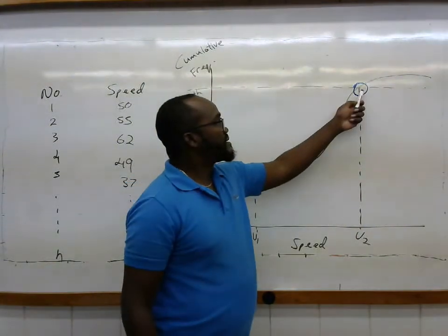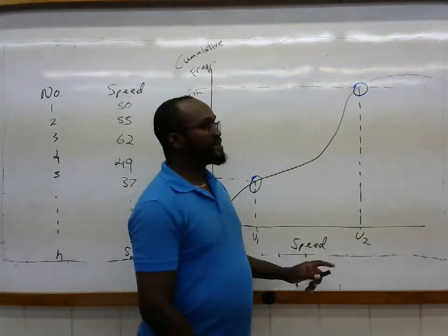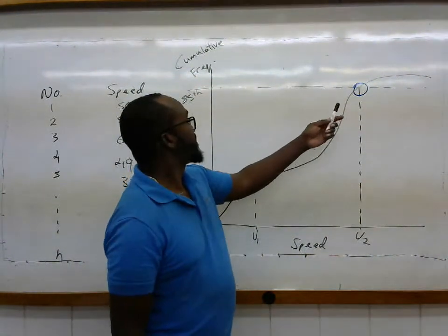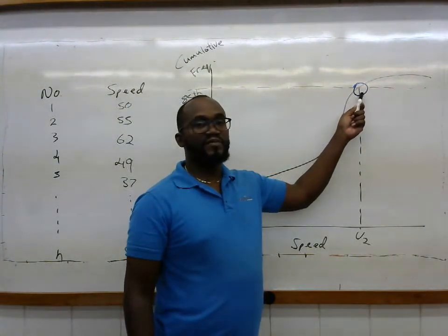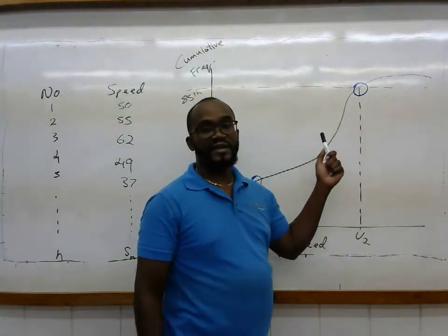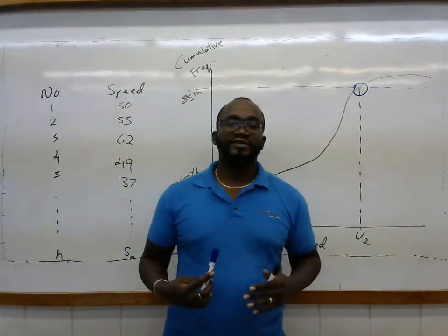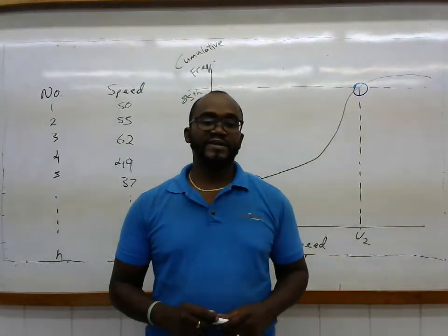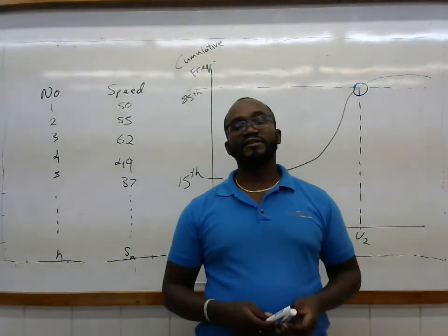When we consider traditional means of setting posted speed limits, it is typically done using the 85th percentile speed. That is, the speed at which we would find 85% of the driving population or less driving. The theory behind that is that the majority of the driving population would drive at a speed that is considered reasonable for the ambient conditions.